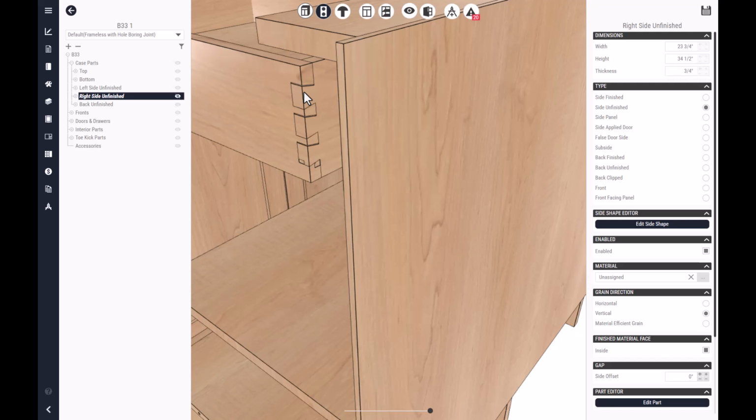Then remember that the remaining full dovetail shaping must still be completed after the nested CNC operation or on other equipment. For a dovetail drawer intended to be completed through CAD Builder's CNC setup, follow the half-blind dovetail video instead. If standardized drawer box heights are being used, confirm that the pattern finishes with complete pins and tails. Before releasing a new dovetail setup for production, machine and assemble a physical test joint using the same material and production method planned for the job.